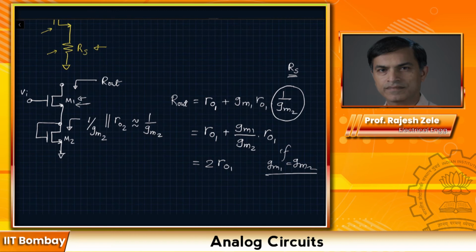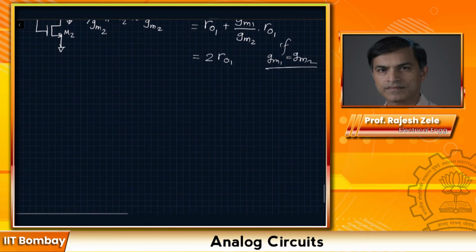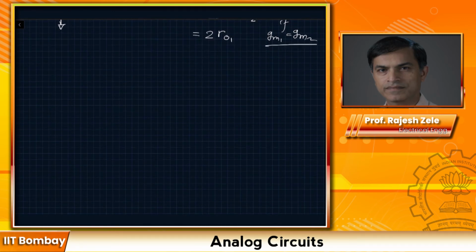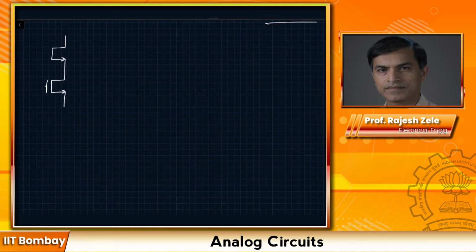The next example we're going to go through is going to be looking like this, and we're trying to figure out what is the R out here. Let's assume that both inputs of the transistor are AC ground. In this case, we can tell that the resistance looking down here is going to be R out of transistor M2, and that is going to get multiplied by the self gain of this transistor.